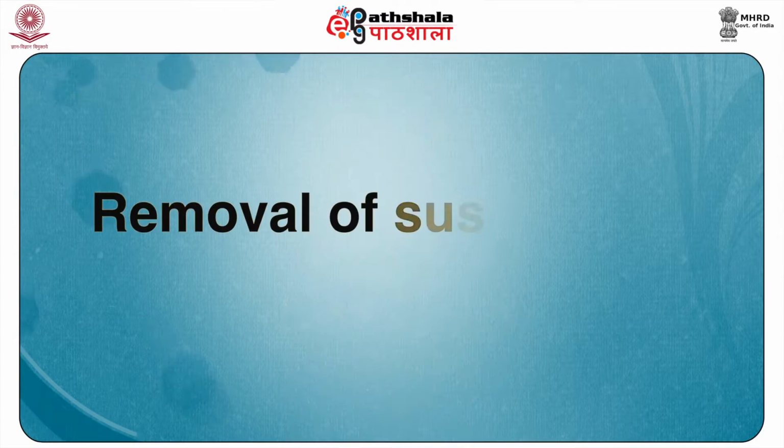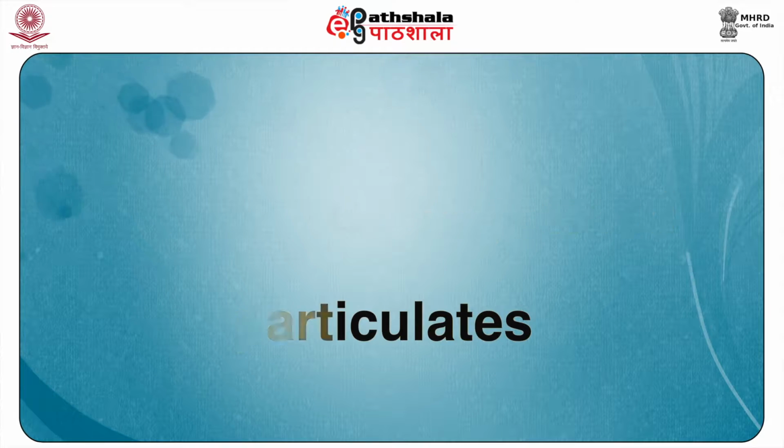That results in the recovery of valuable material for further use. The other aspect is removal of suspended particles. Particles can be removed from air by a variety of physical or chemical processes. Some of the common types of equipment are cyclones, scrubbers, electrostatic precipitators and baghouse filters. The collected particulates can be removed from the equipment and disposed in a landfill. The important characteristics of particulates on which the selection of the collection device depends include corrosivity, reactivity, shape, density and especially size and size distribution.